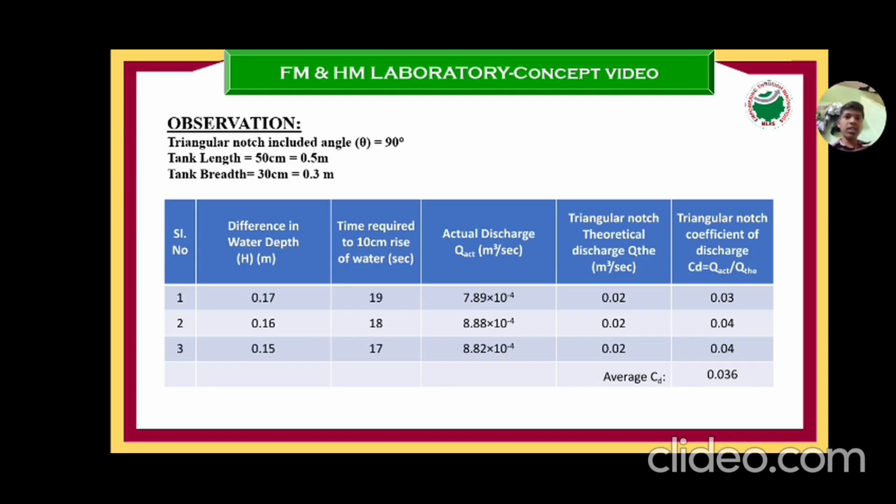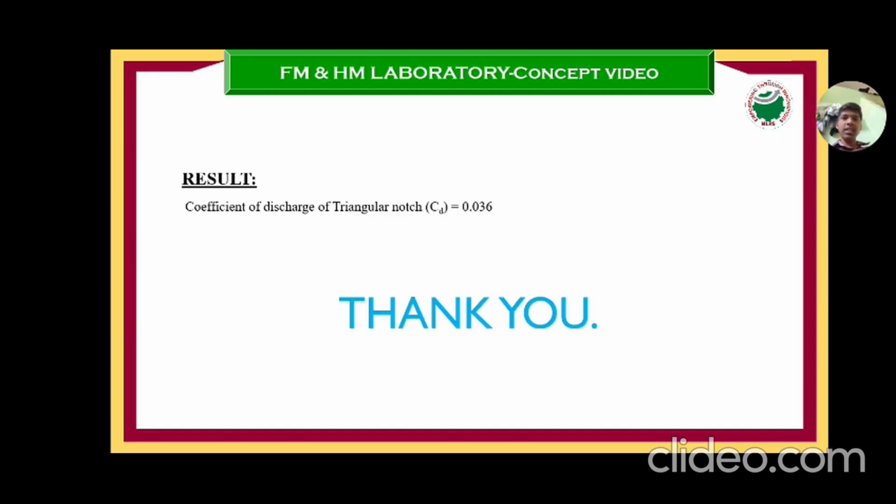Observations: triangular notch included angle 90 degrees, tank length 50 cm, tank breadth 30 cm. Results: coefficient of discharge of triangular notch, CD, equal to 0.036. Thank you.